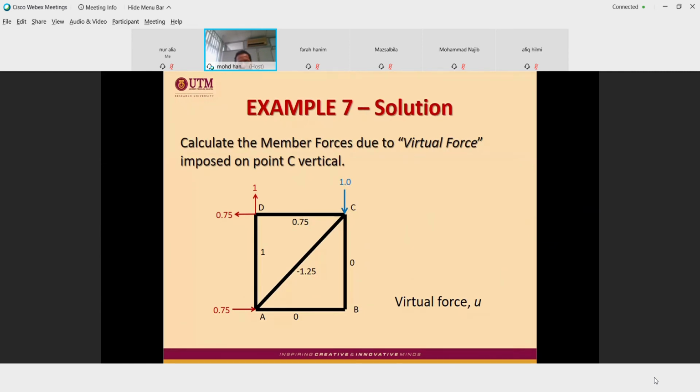Okay. So this is a very simple truss. What is the force in the member? In this case, we have to be clever and make a quick decision. Member CB and member AB, AB and BC, are zero force members. Why are they zero force members? Because members BC and BA meet at a joint where there is no external force.